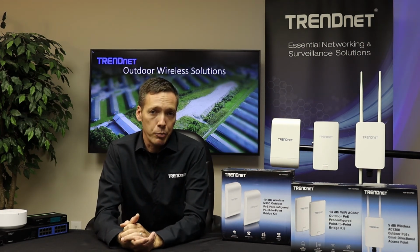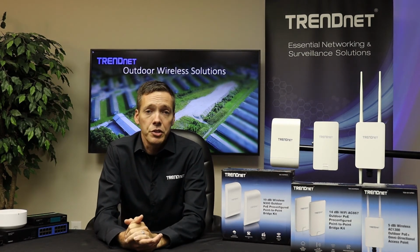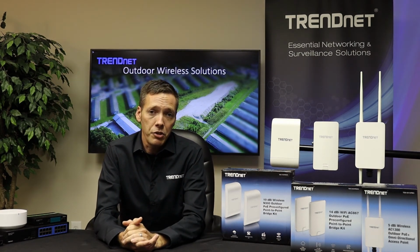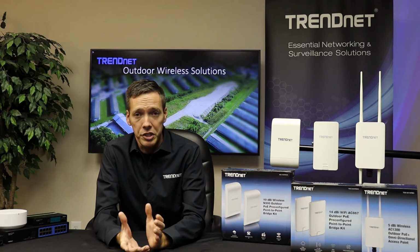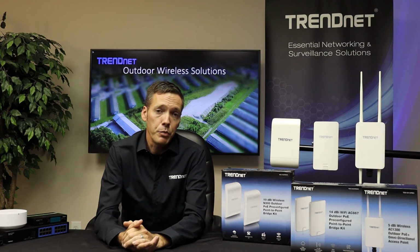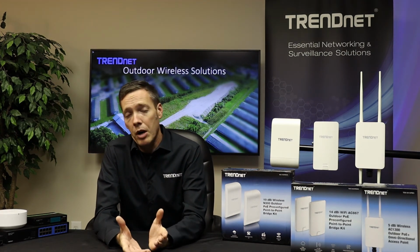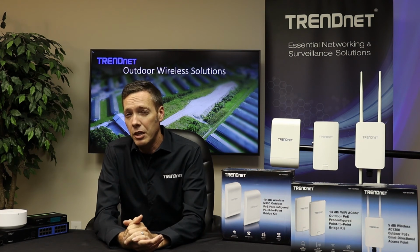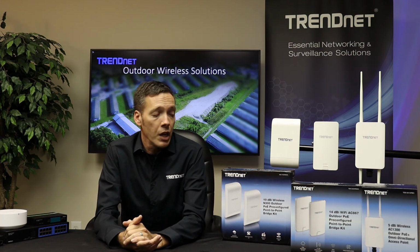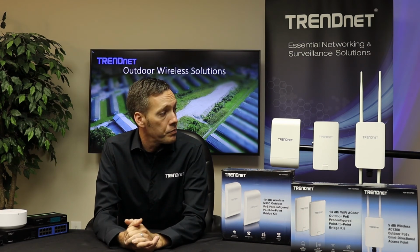The great thing about the pre-configured kits is that they are all pre-configured, so there's not very much programming that you need to do. The bridge is already established, and they come with their own PoE injectors. The idea is you power them up, point them at each other, and you're good to go. You probably do need to do a site survey, so you may need to go in there and change the channel, but the idea is that it really does cut down the installation time.